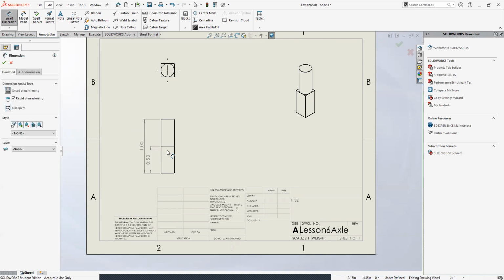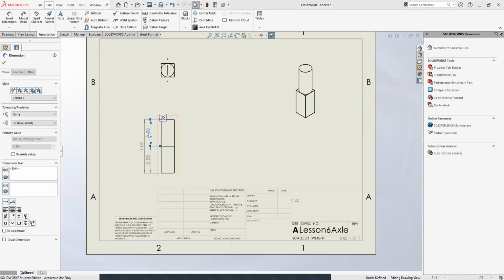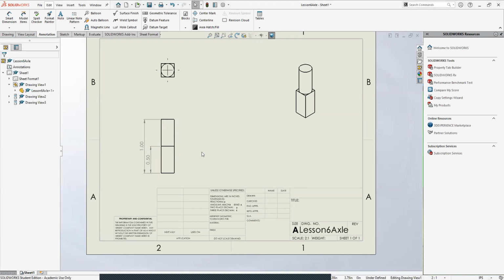What you definitely shouldn't do, though, is something like this, right? Kind of like how before I said don't give extra dimensions. Don't do this, because if you gave them the inch and the half inch, they could calculate that this was half an inch. So don't add in the extra dimensions if you don't have to. And usually you shouldn't have to.